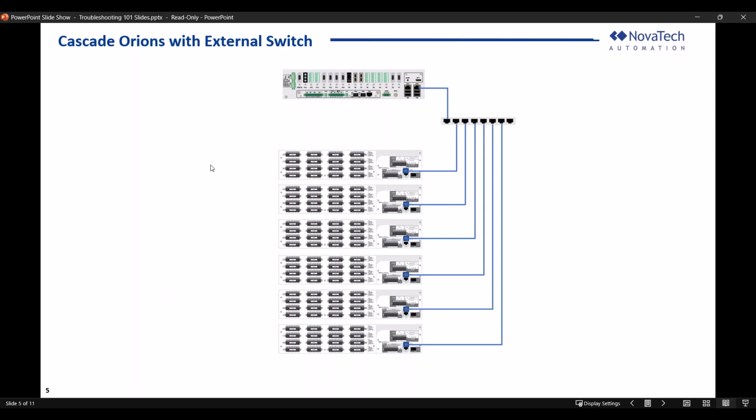Instead of having separate NCD files on each of these units, a DNP server list here, and then a matching point list up at the top to pull it using DNP, which works and a lot of our customers use, to save time producing a matching point list we do have a cascading protocol that allows you to configure multiple Orions in one NCD file.